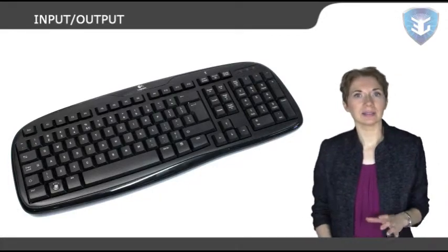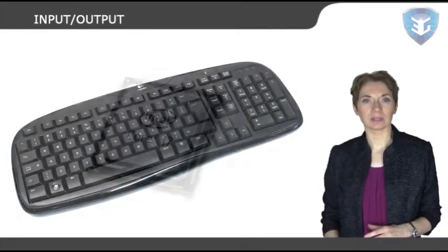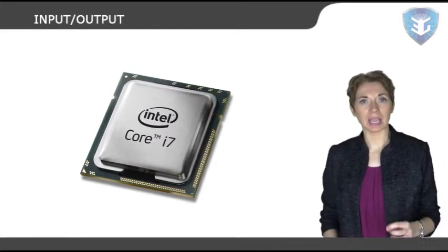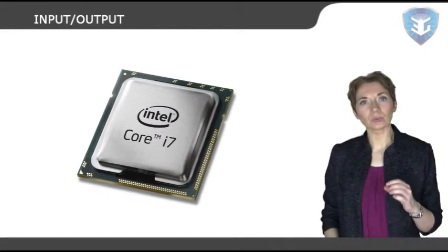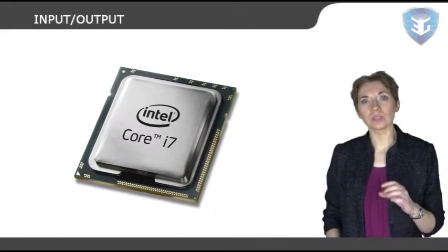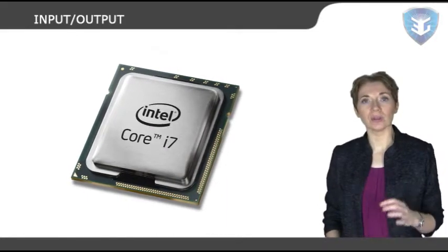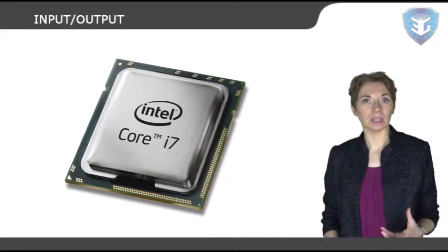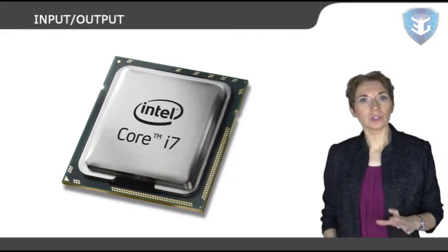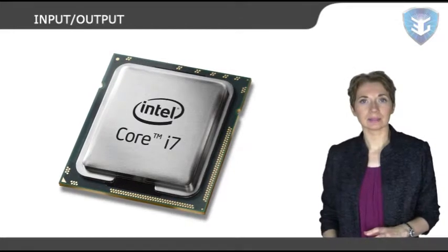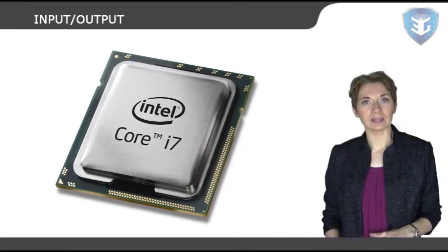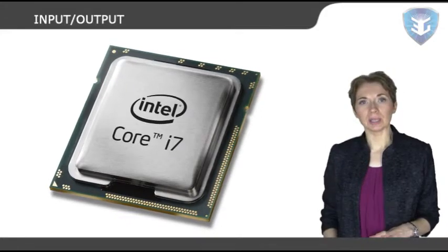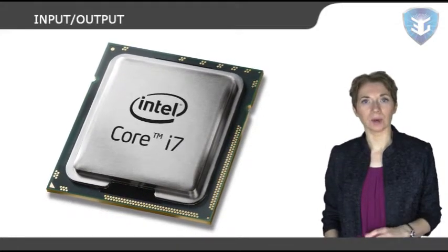Each I/O device is assigned a unique set of addresses. When the processor places a particular address on the address lines, the device that recognizes this address responds to the commands issued on the control lines. The processor requests either a read or write operation, which is transferred over the data lines. When I/O devices and the memory share the same address space, the arrangement is called memory-mapped I/O.